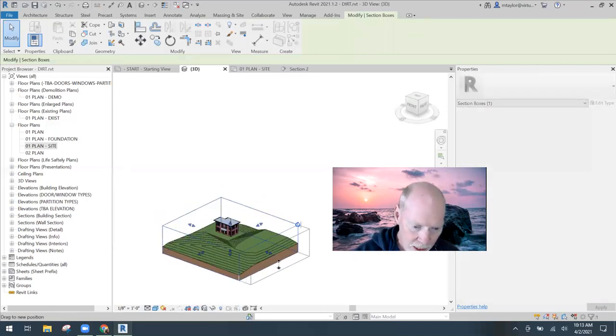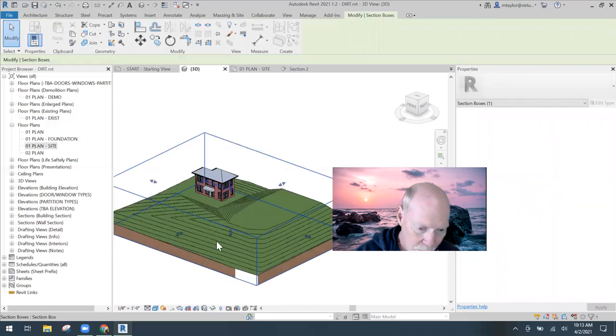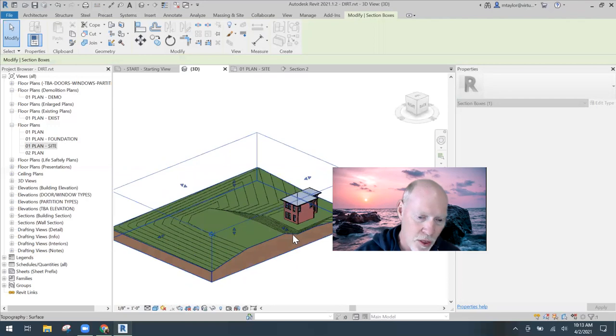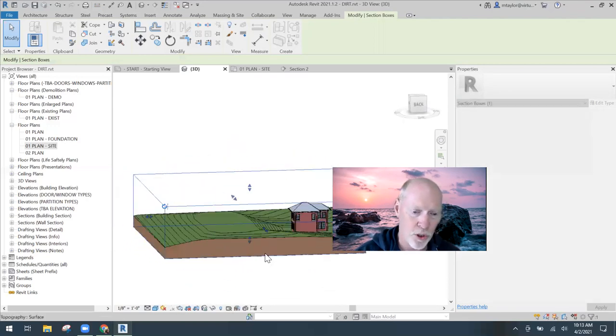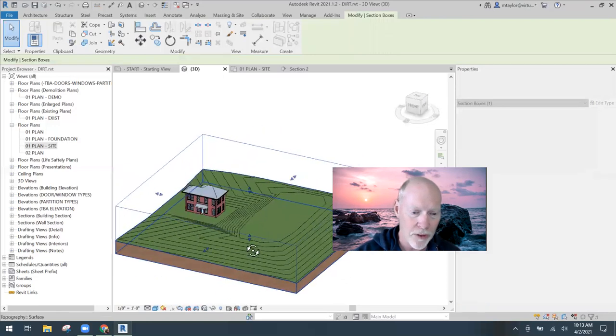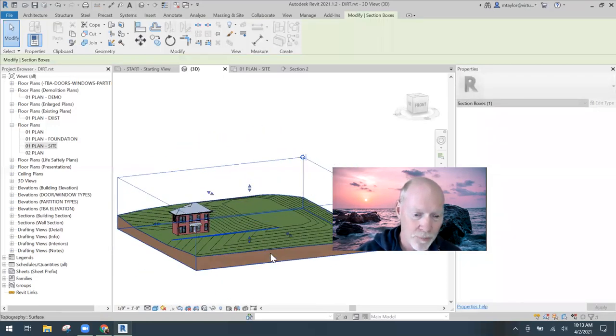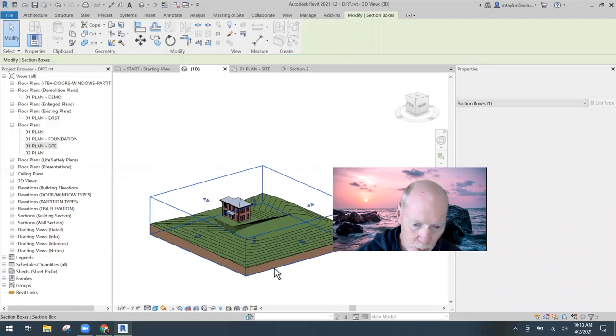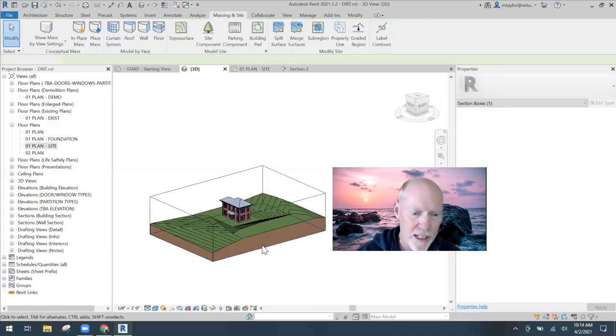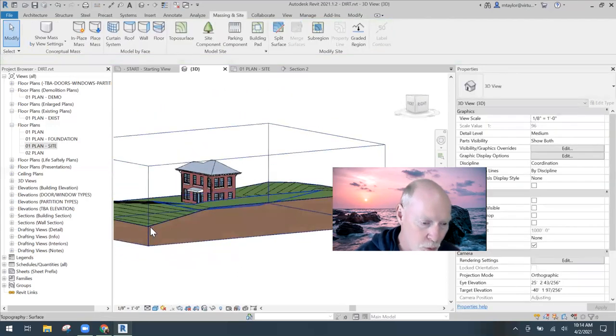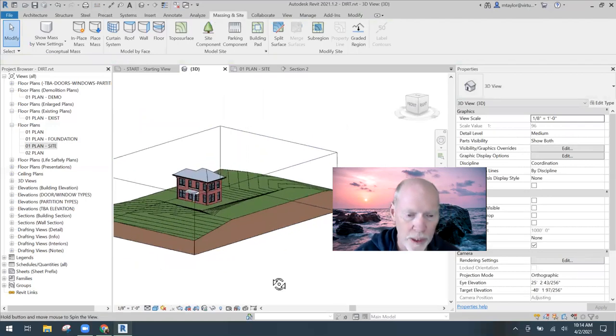And I'm just going to pull this out of the way a little bit. Oop, got past the corner there. You've got to intersect the object, your topo surface. So there we go. Look at that. We've got ourselves a hill. And when it intersects, I'm just going to push this over. When it intersects, you can see that it is cutting through the real topo.